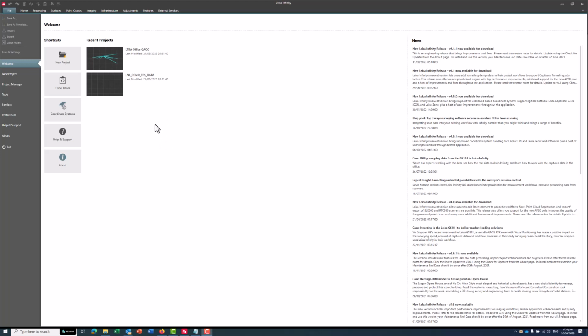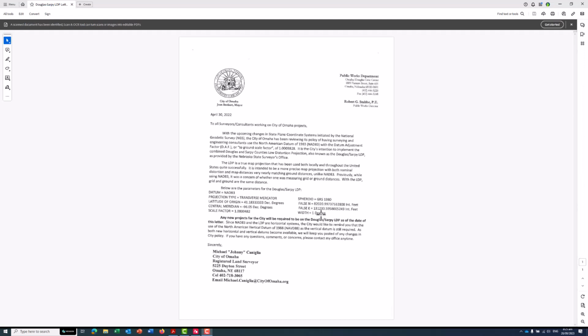States. In this video, I'll be discussing how to create a custom projection and coordinate system in Leica Infinity. A low distortion projection is a type of projection intended to either minimize the differences between grid and ground distances or mostly equalize them. In this case, I have a letter from the city surveyor for the city of Omaha, Nebraska, and they're using a low distortion projection for Douglas and Sarpy counties. And they helpfully have the parameters all enumerated here for surveyors and consultants working on City of Omaha projects. I'll use this as an example of how to set this up in Leica Infinity.